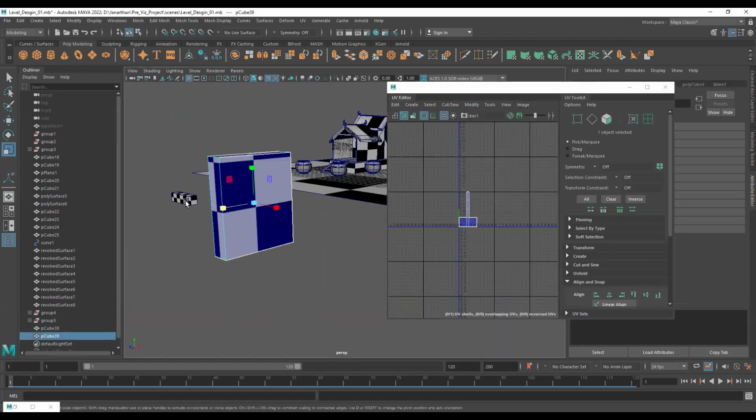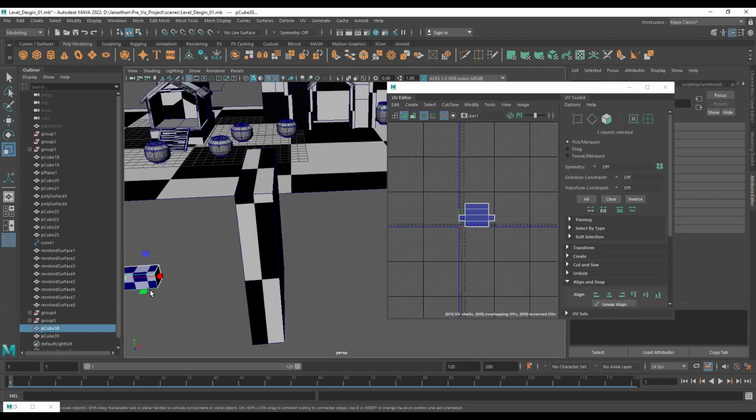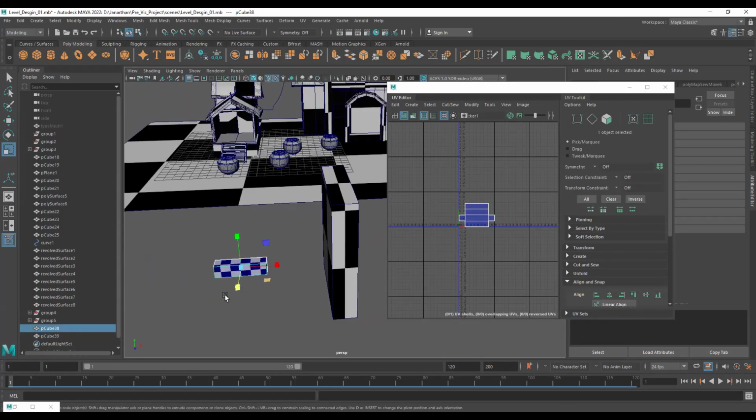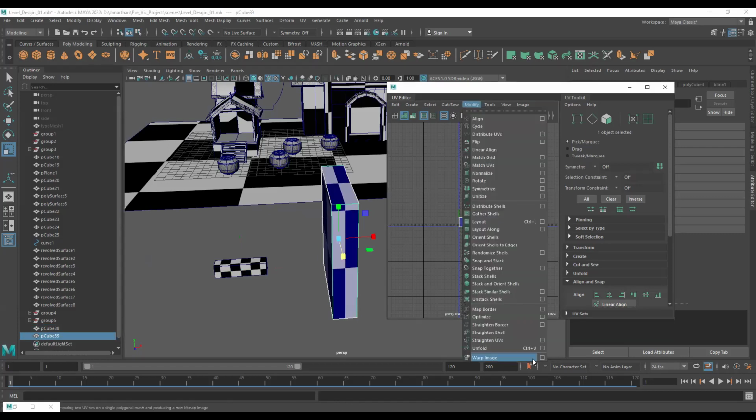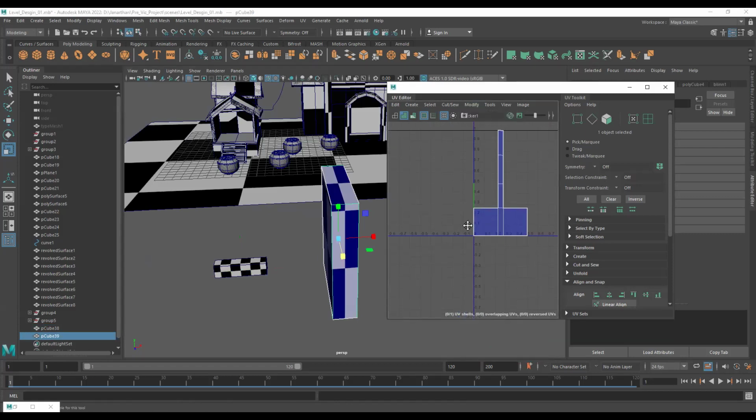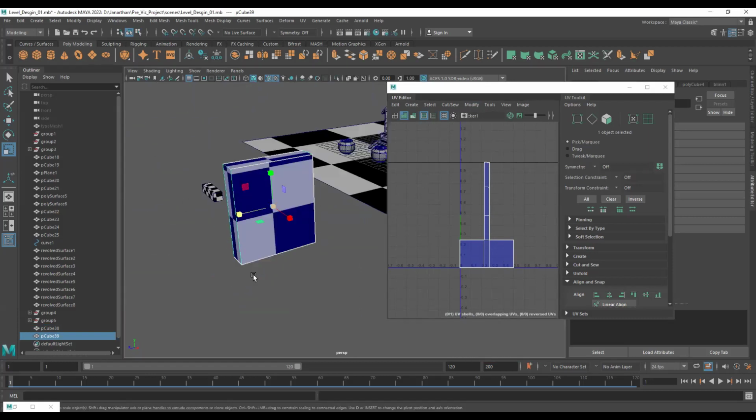So UV is very simple. First, you try this method, because this method you have to project on each side, then flip it, then select the edge, then move and sew UV, then layout UV. Then this method, select this, unfold, option box, legacy, and apply. Here it is straight, that's why we need it as a straight. So we need exactly looks like the object which we select. Then we have to apply the checker. Then we can understand whether the UV is correct or not.